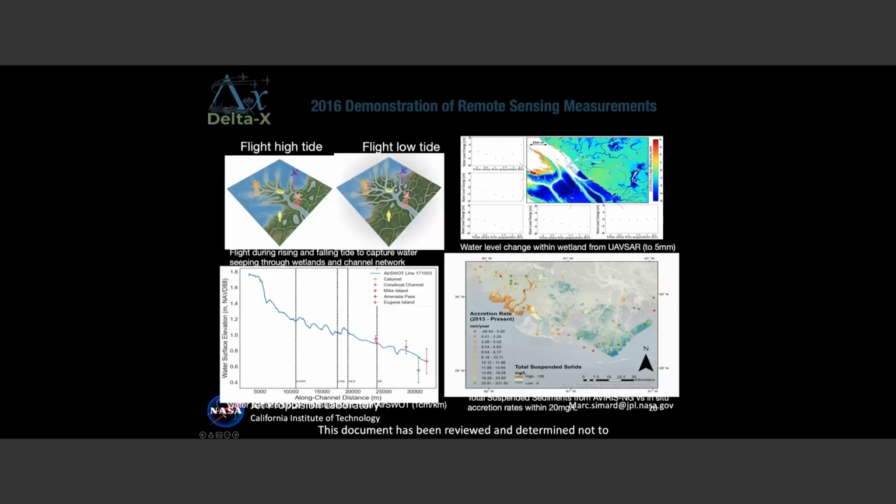measurement or estimate of sediment, total suspended solids or sediment within the water column. So you see in brown here, it means that we have very high, 100 milligrams per liter, contents of mineral sediments, but in the Terrebonne Basin, the concentrations are much lower. So remember, this Atchafalaya Basin here is building land, and this one is losing. So this is what's expected when you don't have sediment, is that you will most likely lose land.